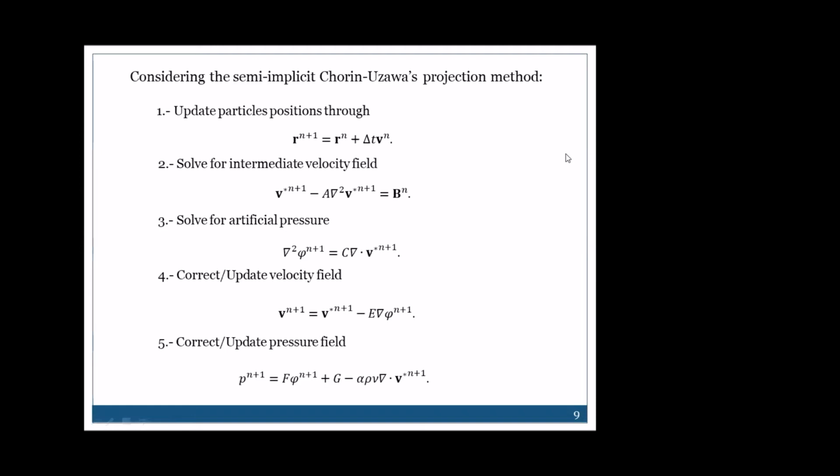Yes, it is Meshfree because you don't need these meshes to solve the governing equation. You only need the position of the nodes, and with these positions of the nodes, you interpolate the variables, taking into account the constraints of the physical equations. But you don't need to construct these meshes with predefined relationships between the nodes. So the nodes can evolve in time without any constraint. For that reason, they are called mesh-free or meshless methods.